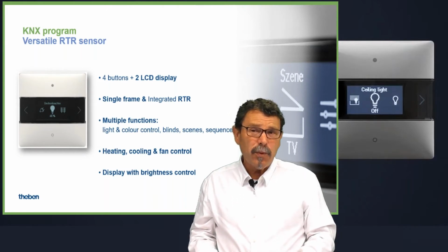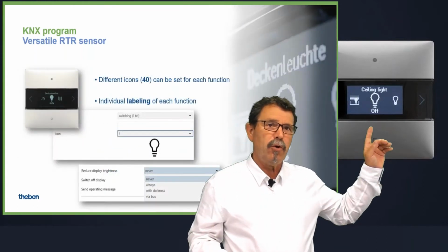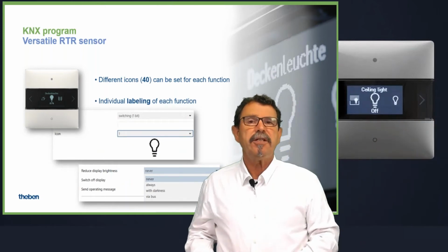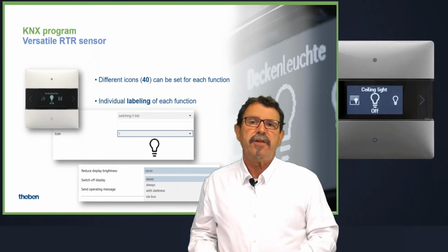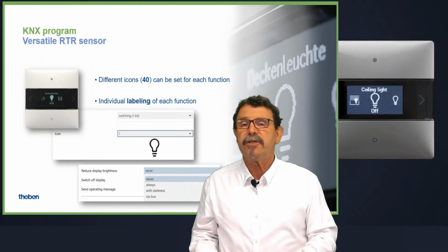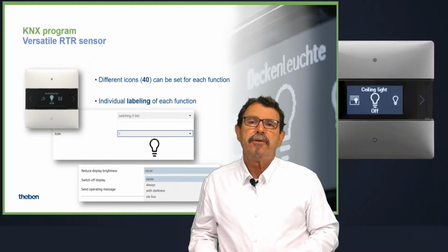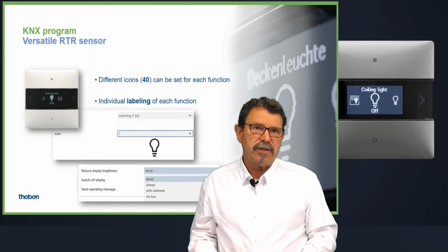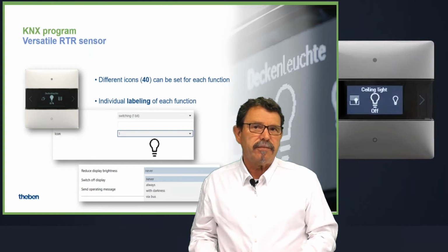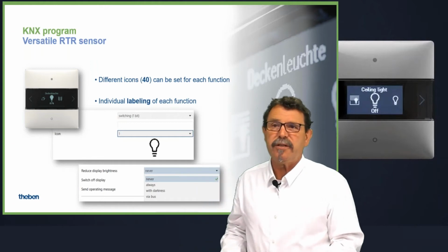And we have the option as well on long press function. So that means if you press longer time on this button here, then we change the display, and you do have just the RTR settings, so your base set point, for instance, or the current room temperature, or the operating mode is displayed finally. And then with the up and with the down button, you can select the reasonable function, or increase or decrease finally the desired room temperature. Yeah, that easy.